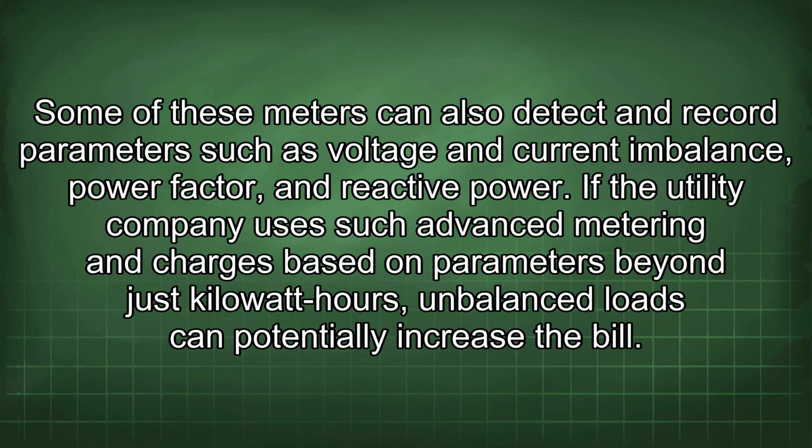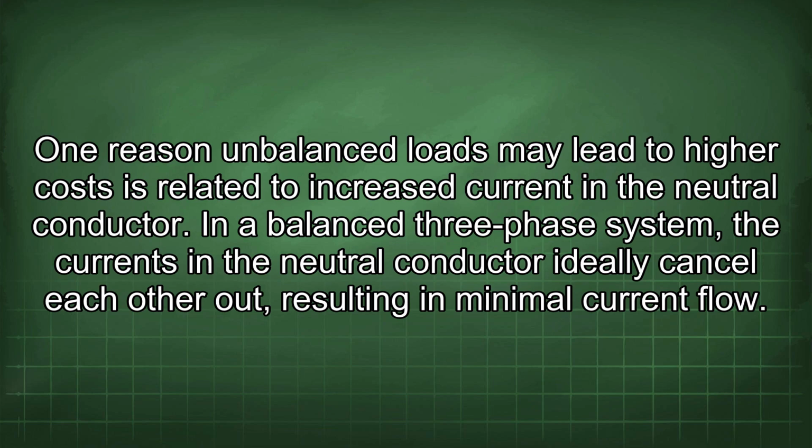Some of these meters can also detect and record parameters such as voltage and current imbalance, power factor, and reactive power. If the utility company uses such advanced metering and charges based on parameters beyond just kilowatt-hours, unbalanced loads can potentially increase the bill.